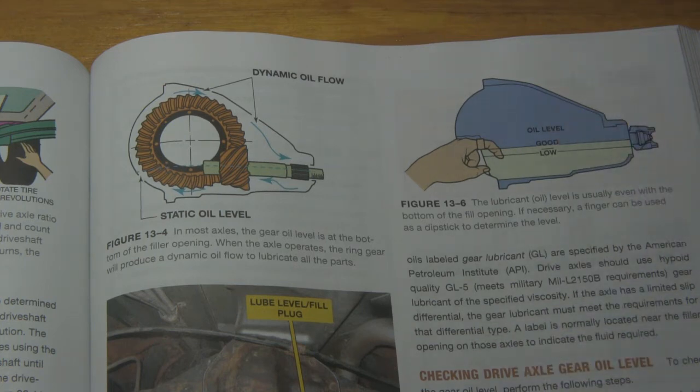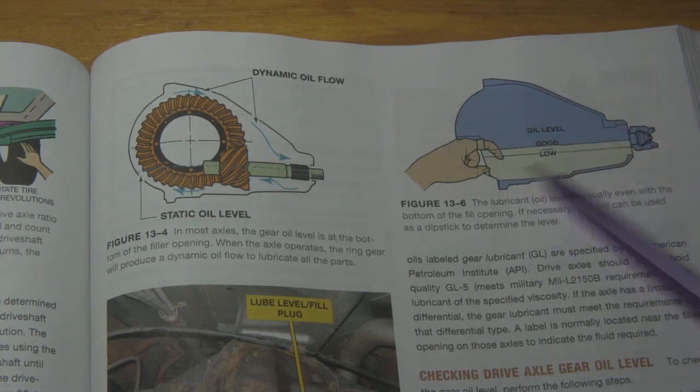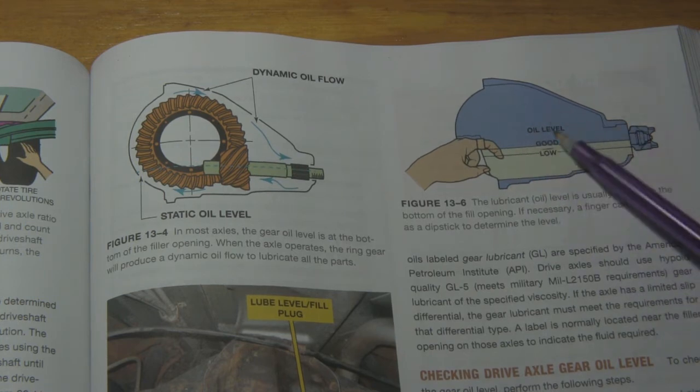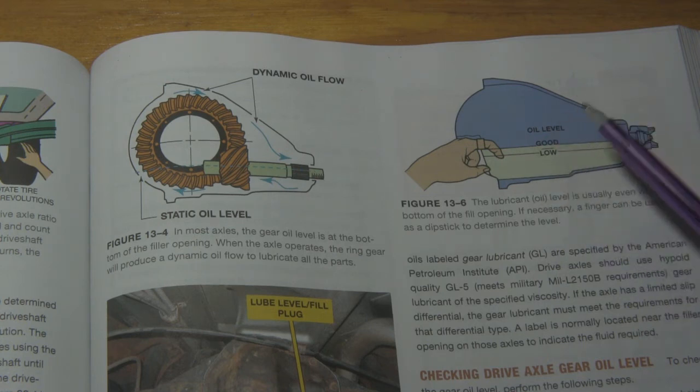Pay attention to the fill procedures, because some of these manufacturers design these axles and they're very, very sensitive to overfilling. And so if you think about what happens if you overfill, you have a tube that runs out to the driver's side and the passenger side from this case right here, and there's a seal out there. And so if you have too much oil in the case, you could end up with a situation where you start to have axle seals that leak.